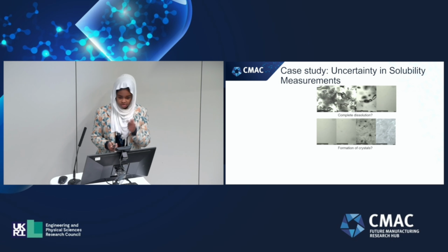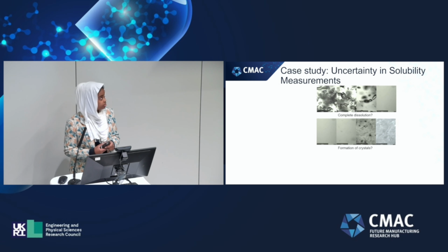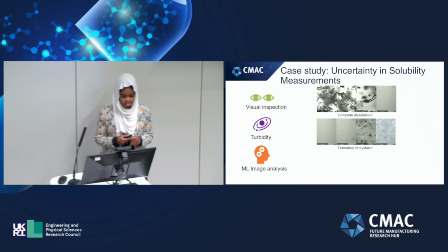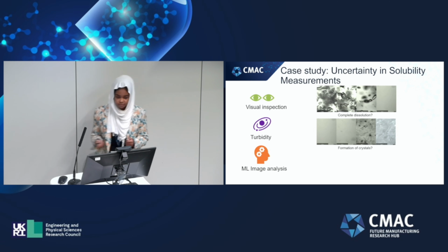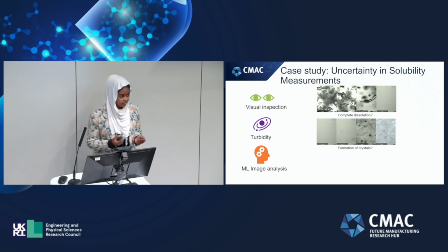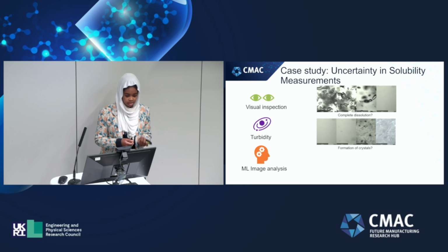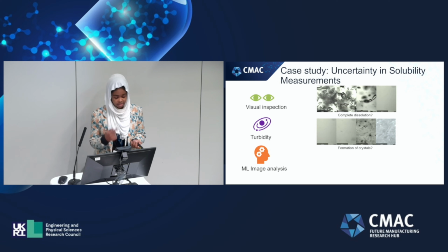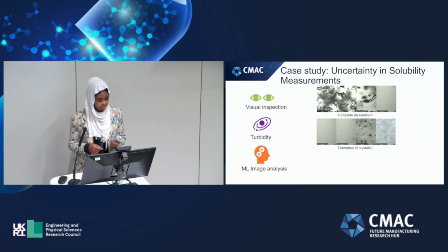I'm looking into the uncertainty of solubility measurements by looking at three different methods. First, visual inspection, so looking at the actual images and finding the point where there is complete dissolution and formation of crystals. Then comparing that with turbidity, which is a measurement given by the Crystalline software using light transmissivity.